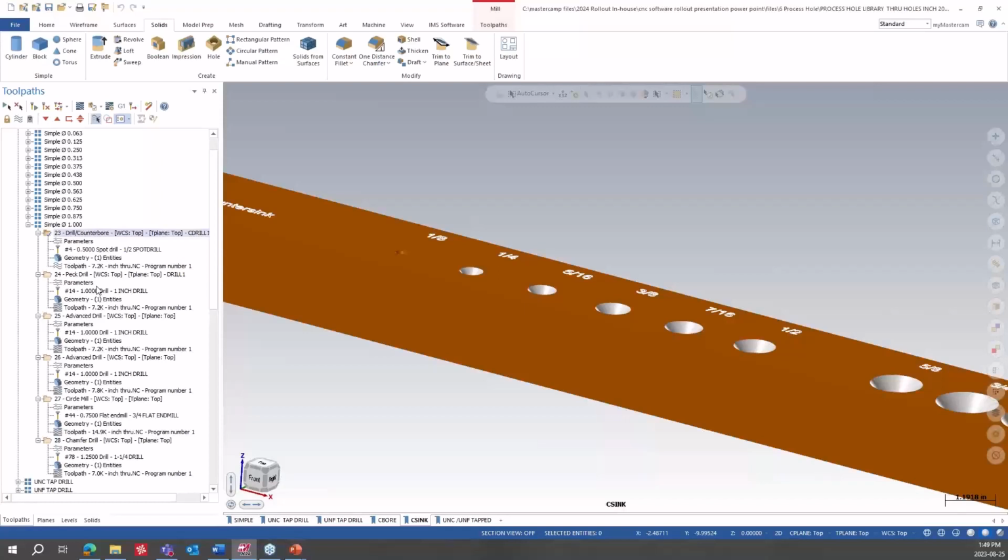Because in mine, for example, on a 3/8 counterbore, I'm making the counterbore itself 5/8. In some shops, that might appear as 3/4. In some other shops, it might appear as 5/8 or something else. So that would be dangerous. You'd have to go through your whole process library to check everything and make sure the process is correct to what you want. And you can use any of the processes and apply them to those holes like what I was showing.